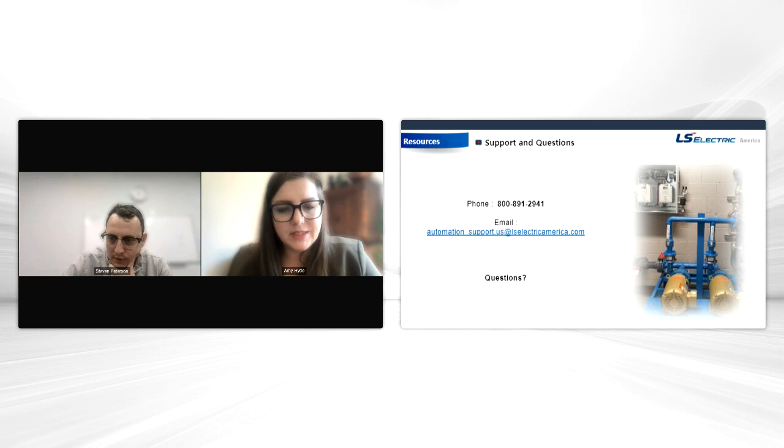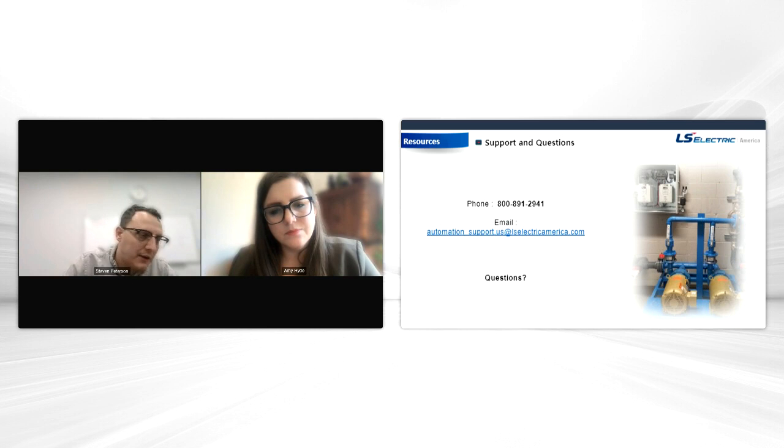We've got another question that says, do I have to use PID on the H100 Plus? No, you don't. You could just use the basic macro, which is really just no macro at all. It's kind of like none. A lot of people do that. They just follow a 0 to 10 or a 4 to 20, and it's direct speed control. So you don't have to use PID, but we're talking about it now because if you're not doing the basic macro, most of the time people are doing PID or lead lag or something like that. So. Sounds good.